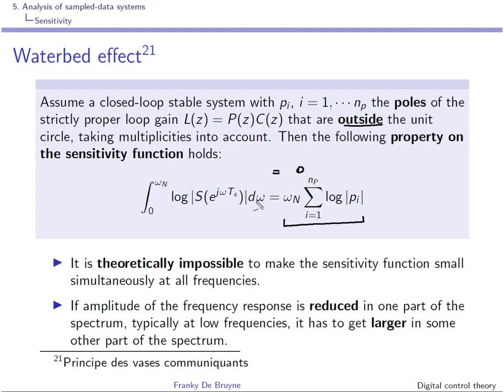This means that if you look at this log of the sensitivity function in a linear scale for omega, and what you have here on the y-axis is the log of the modulus of S, right?